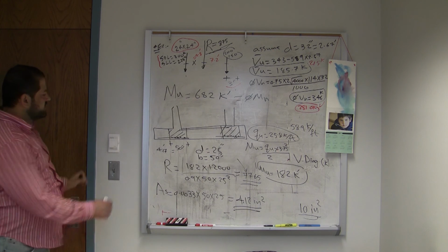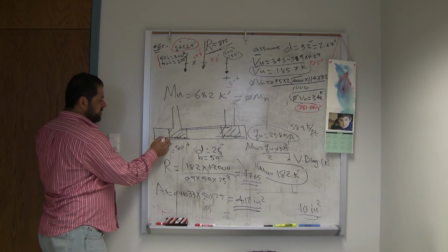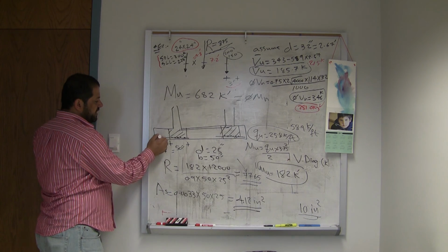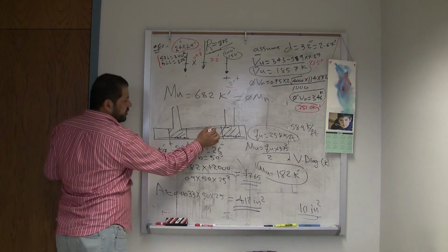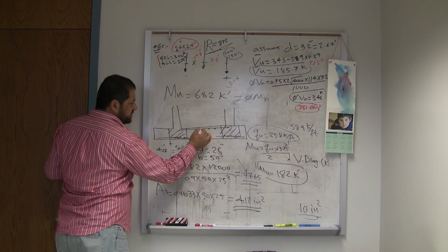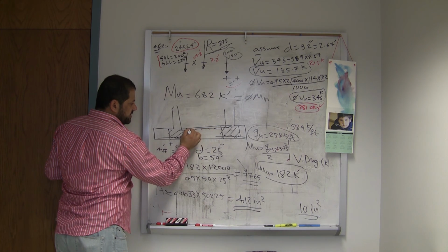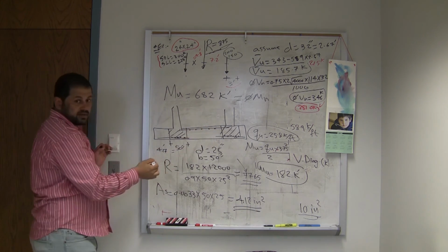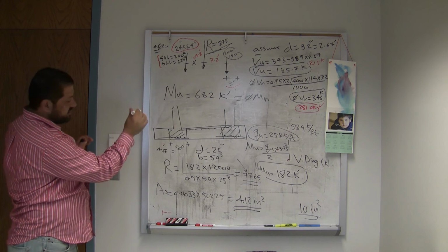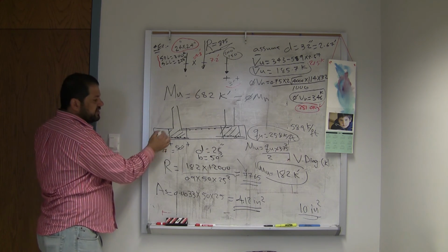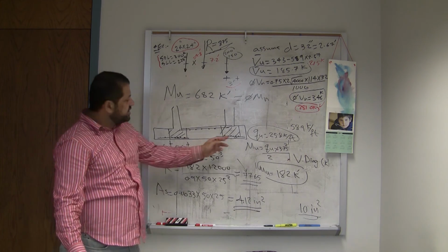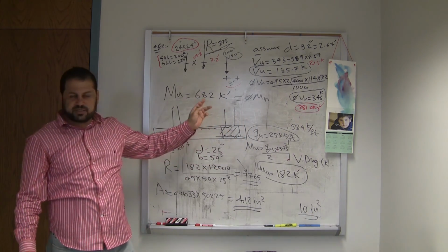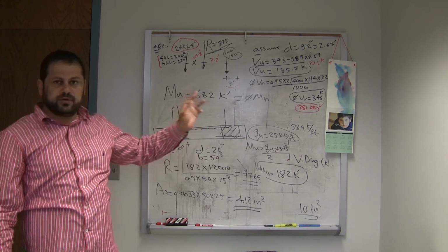Also, in these locations, when we don't have any steel in the other direction, the steel here is non-structural in the other direction. And here we provide shrinkage and temperature steel. Rho for shrinkage and temperature is 0.002 for footing.